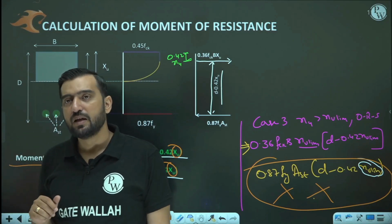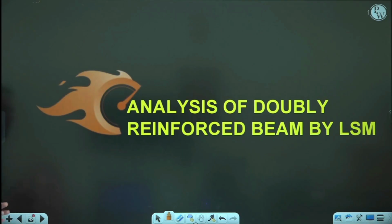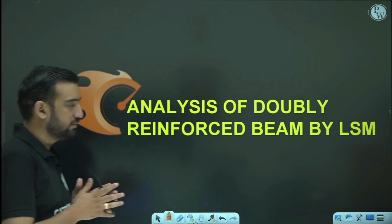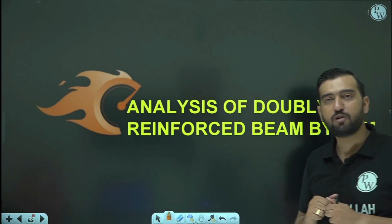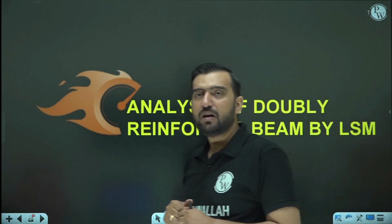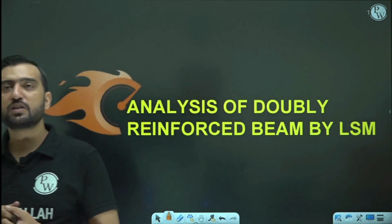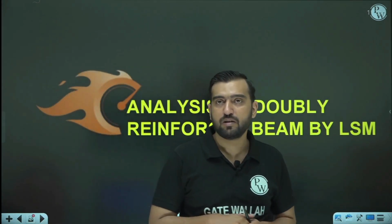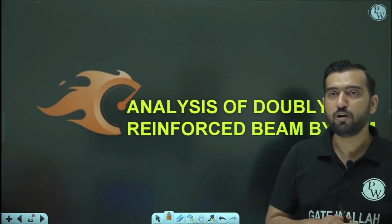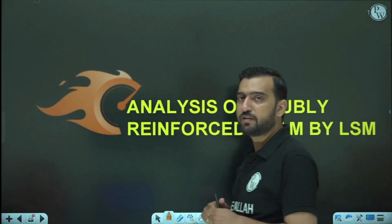Okay. Next, my dear friend, now we will be switching on to the doubly reinforced section. In the doubly reinforced section, the things are 80% same. Okay. One difference is going to come on the compressive side, because on the compressive side earlier only concrete was effective, but in the doubly reinforced section this time along with concrete, steel is also there. Many of you might be thinking, what is the necessity of steel on the compressive side?